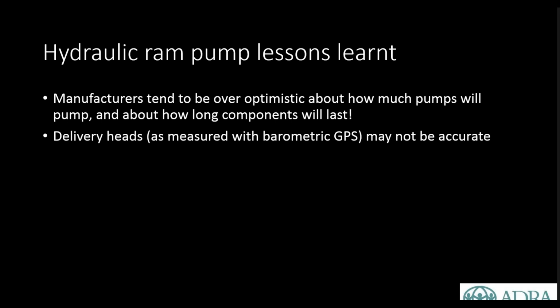The delivery heads, which is the elevation difference between the pump location and the tank location, if they're measured with a barometric GPS, they may or may not be accurate. There's a level of inaccuracy for that, and that may have an impact on how much your pumps will pump as well.